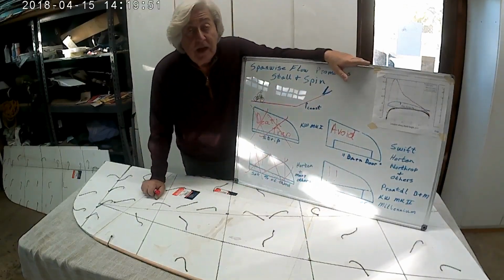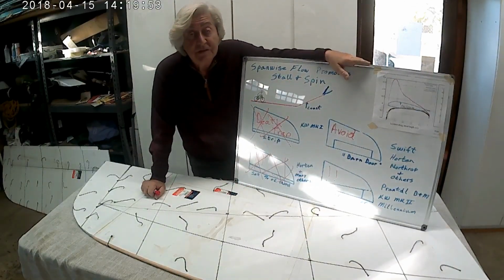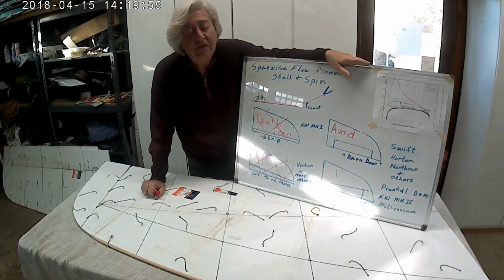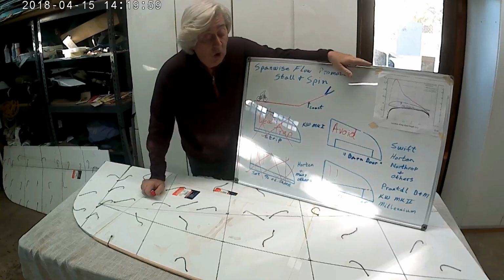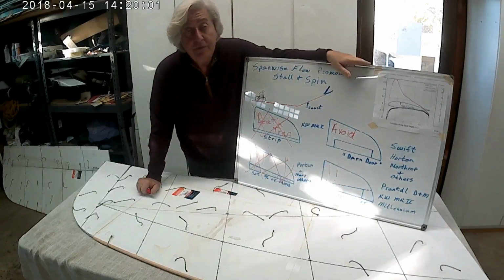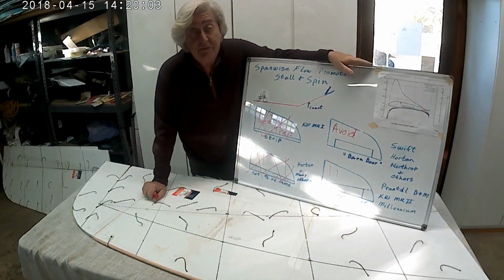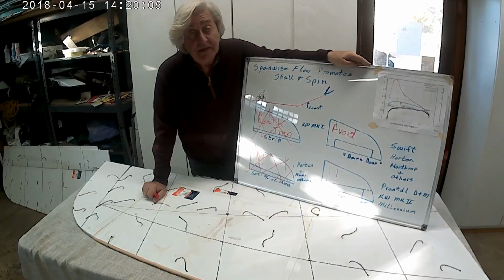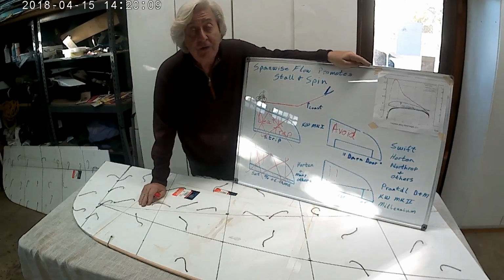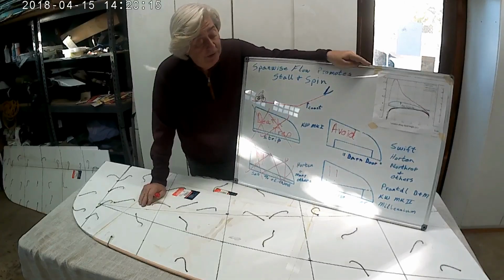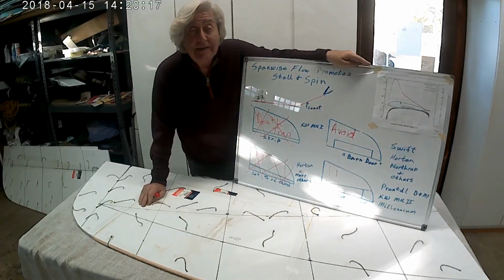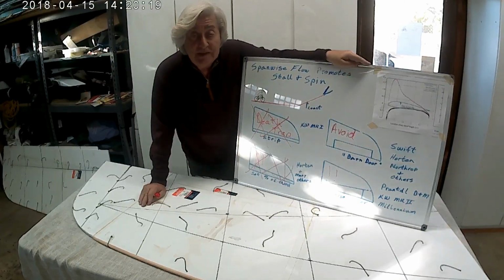But I myself, I've done dozens of flying wing designs. I would never, ever use one of these elevons ever again. Only reverse taper for my designs going forward. It really makes sense. There's three factors at work that help keep the flow attached and going chord-wise, not span-wise, and span-wise flow will kill you. So, there we go. I think that's important insights.